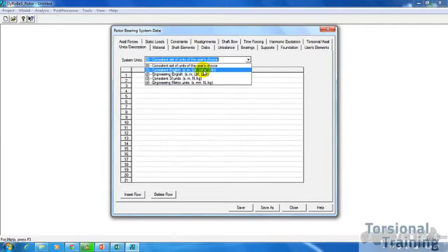Now in certain cases, when you're dealing with some equipment that is sold in Europe or produced in Europe, then you can go ahead and click on engineering metric units. Now there are some ways of saving your files from metric to consistent English or consistent English back to metric. It's very easy to save back and forth. So for example, if you're sharing models across continents and your preference is working in consistent English while your counterparts in Europe have a preference of working in metric, then it's very easy to save a Dyrobes file into a different unit system from the unit system that you started.